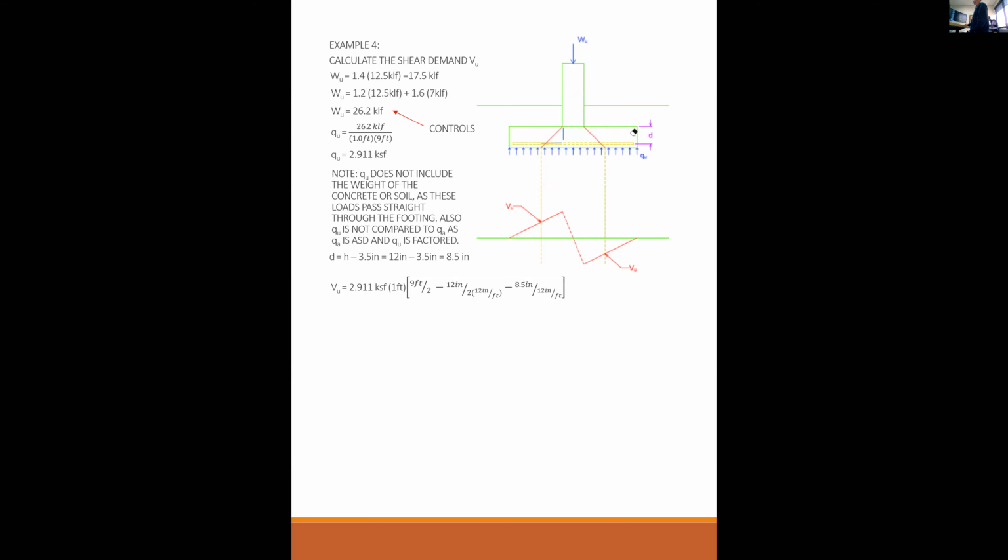D that we know of is defined as the concrete in compression to the center of the steel in tension. That's the D we've been talking about all along. But for measuring where to get the shear, we go that same distance, we just take it horizontally from the face of the wall to our critical section. Okay, is that clear, everybody? Does that make sense?